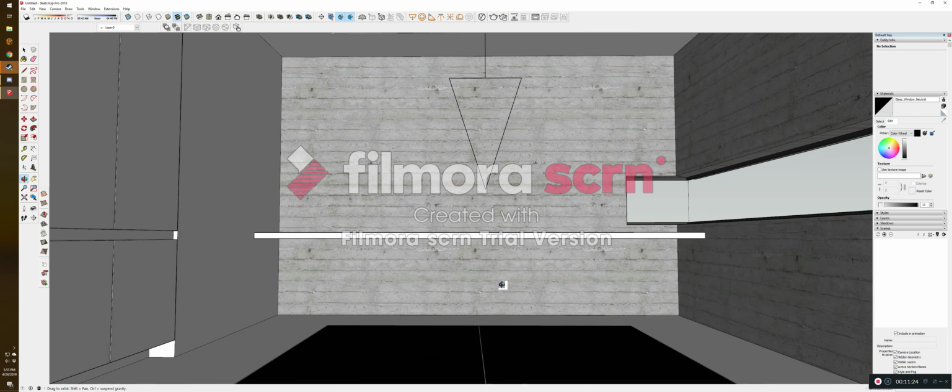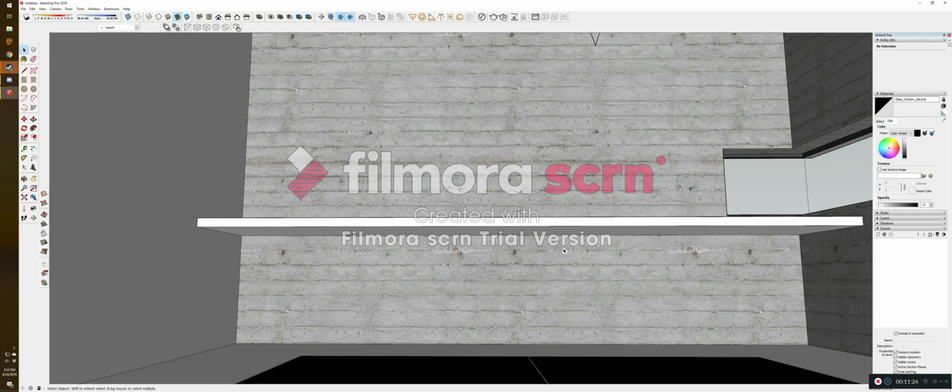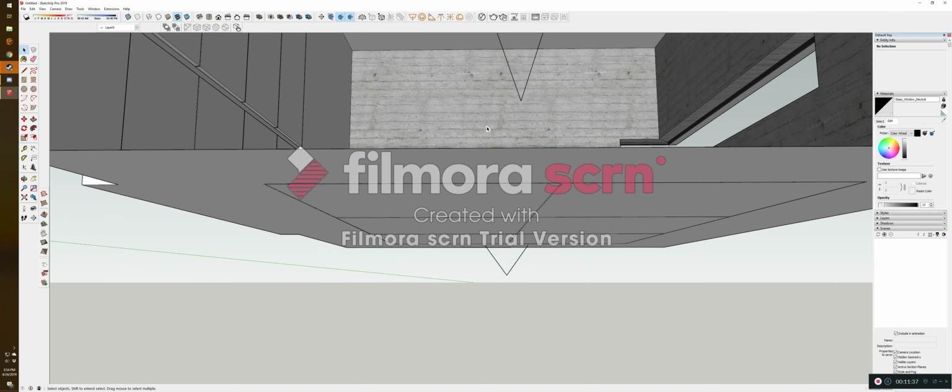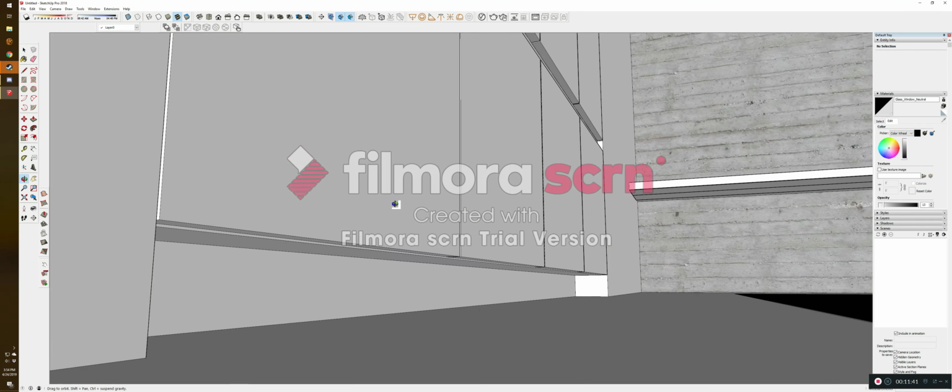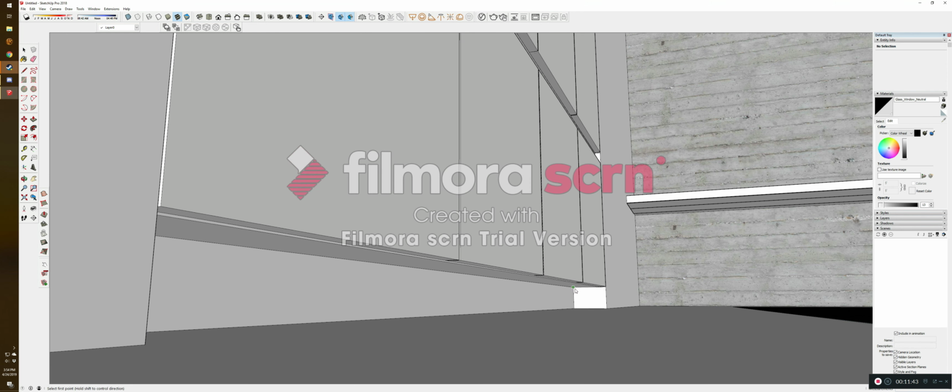I also want the underside of our table lit. So we'll add another box light from there to there. And again, I'm going to offset this 1/16 of an inch. And our last light will be underneath our cabinets, which will just be another box light from here to here.